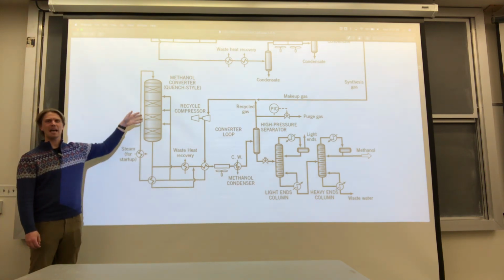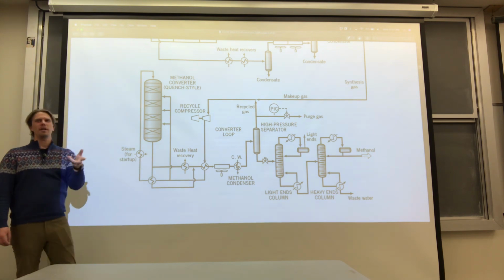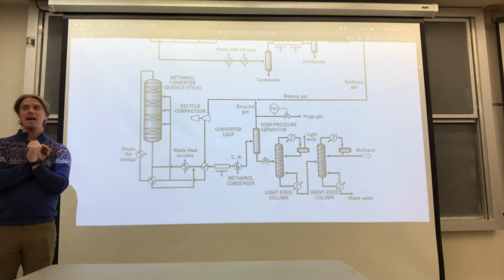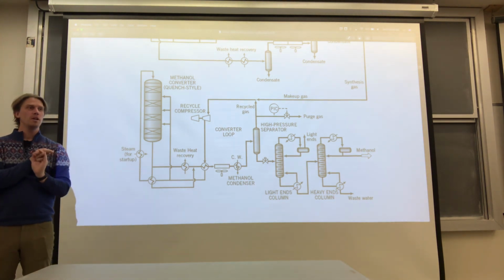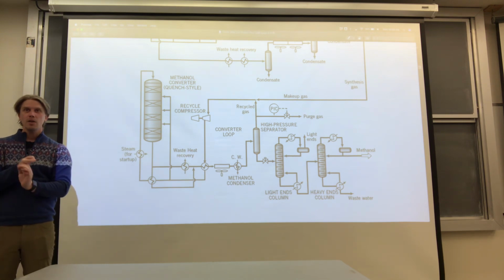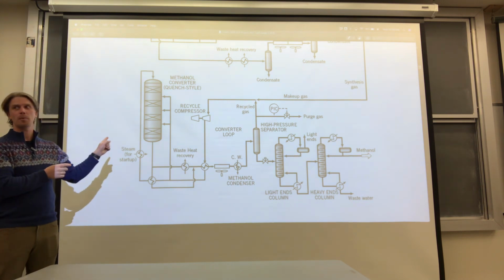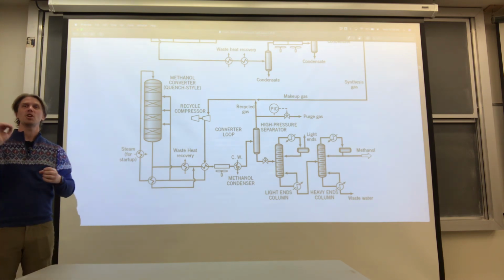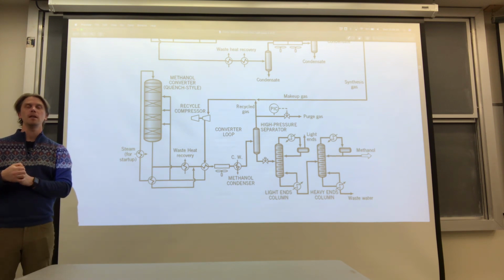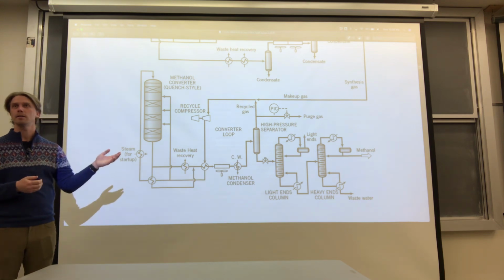If you deactivate the catalyst, there's a couple of things that go wrong. One, you've got to buy a new catalyst. Two, you've got to figure out why your temperature got out of control. Three, you have to shut down the entire chemical process until that problem is fixed. So the biggest cost is probably going to be the delayed profit, because you're not making product, right?